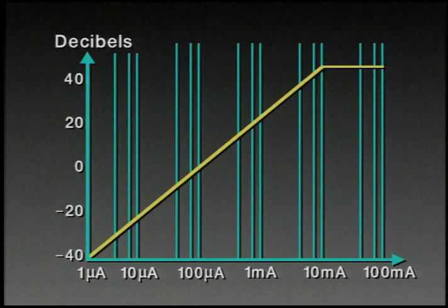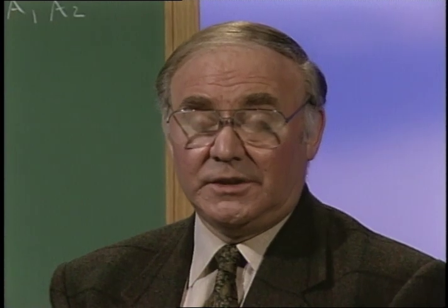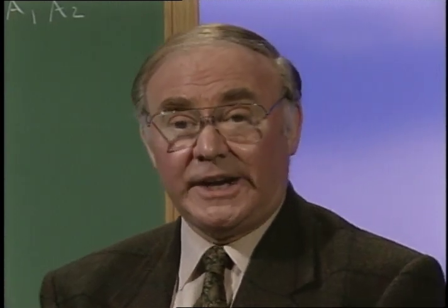Now here we've assumed a beta of 100, and that means that we can get a current gain of 100 out of the circuit before suddenly the gain stops increasing and it plateaus at a gain of 100 no matter how large the tail current is. That may not seem very remarkable, but it's the only circuit, certainly to my knowledge, that exhibits this property. You might think about that and discover for yourself why it is so, and compare it with the type B configuration, which not only does not exhibit this behavior, but in fact exhibits quite significant beta dependence.